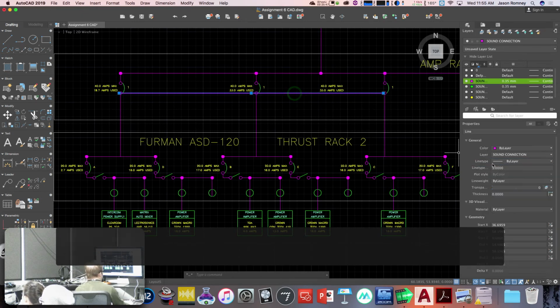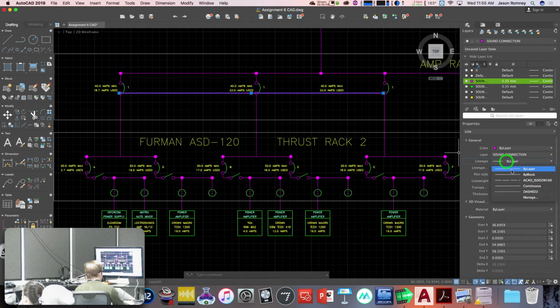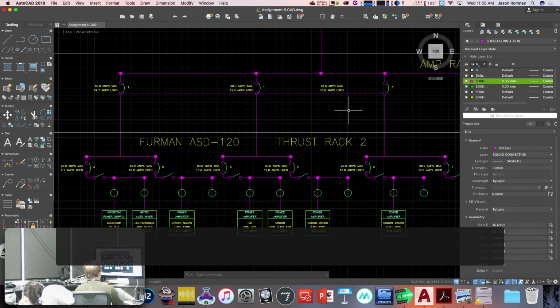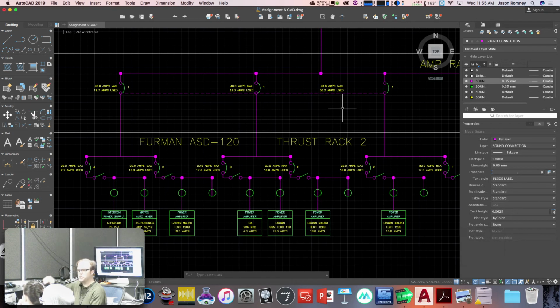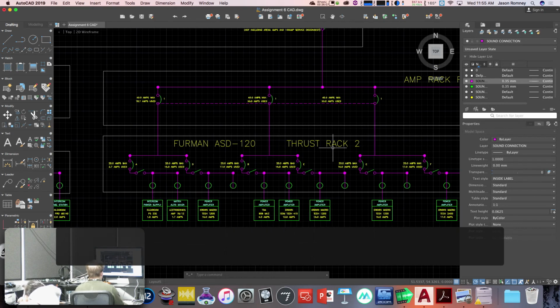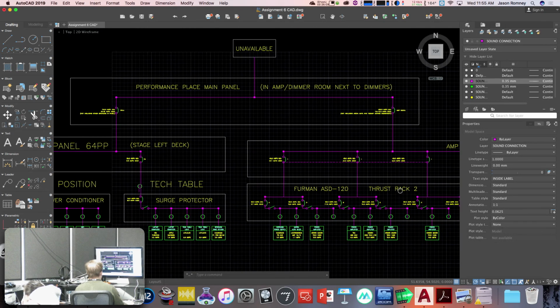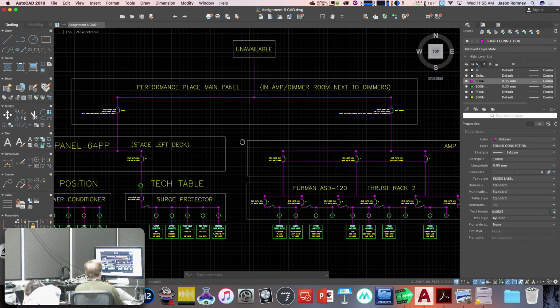But if I grab it and do line type -2, then it'll draw it that way. You could also have line types defined for layers, right? So that every line you draw on that layer gets that line type. You could do that if you wanted to. That's just not how I did it. So that's the basic idea here.